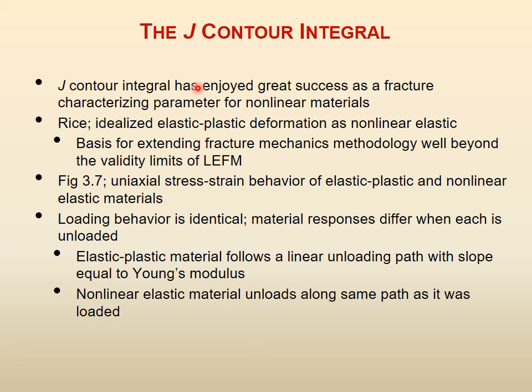The J contour integral has enjoyed great success as a fracture characterizing parameter for non-linear materials. Compared to CTOD, which was very simple, this is more successful as a measure. Rice, a scientist and engineer, idealized elastic plastic deformation as non-linear elastic. This is a major thing.